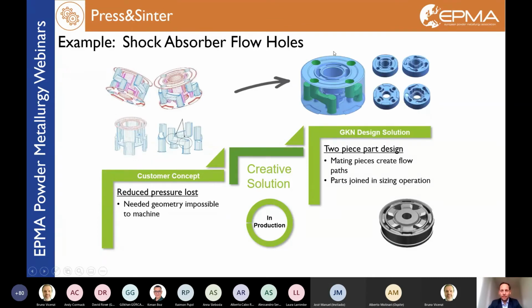Next slide. This is a shock absorber pad, a very common pad for the PM technology. As you can see, here are some oil channels. This cannot be realized even with machining. So what was the creative PM solution? Compact two single pads in compacting, and in the sizing operation join them together to one pad, having this oil channel geometry after the sizing.